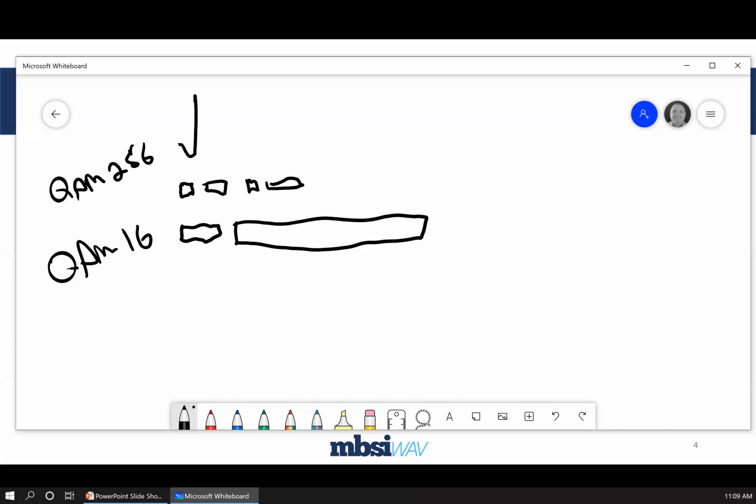If we're going for a type of network where we simply allow everybody to connect and give them a relatively low data rate, then we can go down in modulation levels, and we can allow the network to reach much farther, but the data rate that we're connecting at for those far subscribers is going to be much lower. So we're going to take up more time, therefore we have less overall capacity on the network compared to the capacity-based network where we've built it for speed. All right, drag this out of the way.